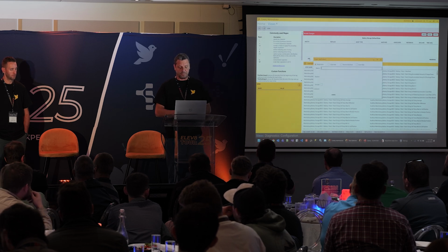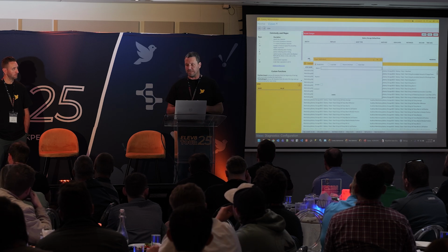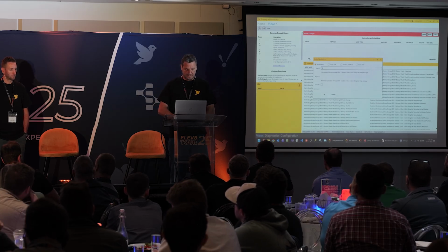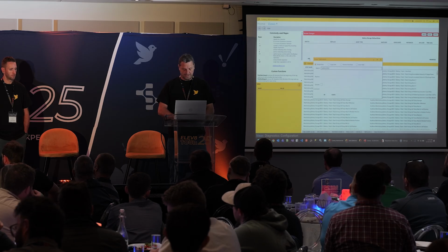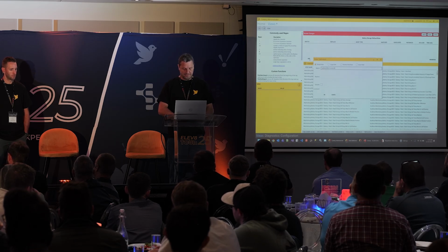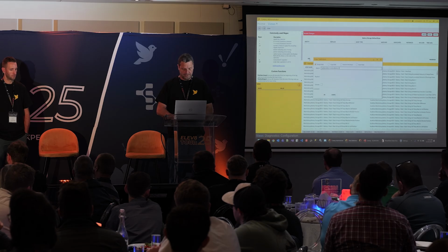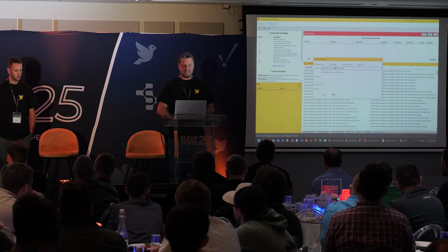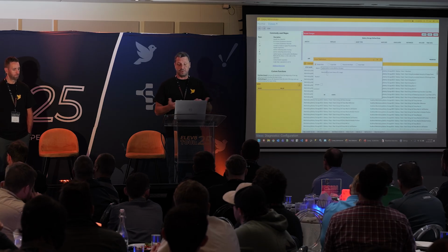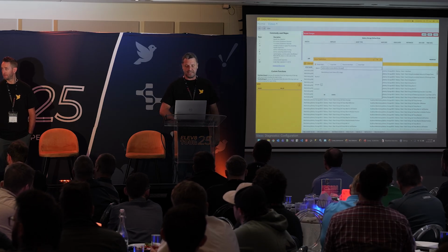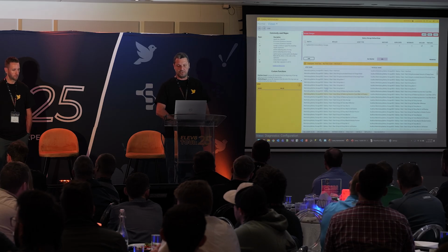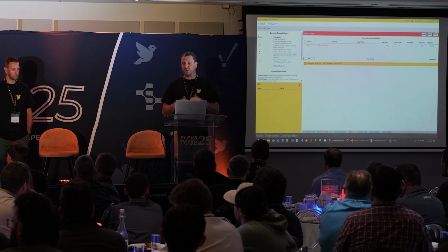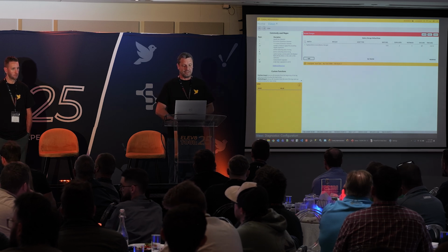So I'm going to create what we call a model rule, which means we're doing some sort of transformation, or in this case, an exclusion. We want to kick these out. So I'm going to say tag name not contains battery storage. As I type this, we try to auto-suggest or find the first tag that matches that pattern, so I can clearly see that I found something. If I say exclude, I can see I've kicked some 3,000 tags out of my model that aren't part of the scope for what we want to share.